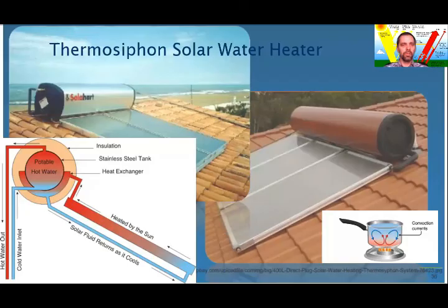Thermosiphon solar water heater. In Mediterranean countries, these devices, because of their simplicity and pump-free operation, are almost in every household. It is actually a solar collector and a water tank mounted above it. No pump is needed due to convection.